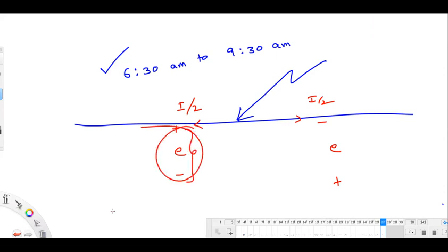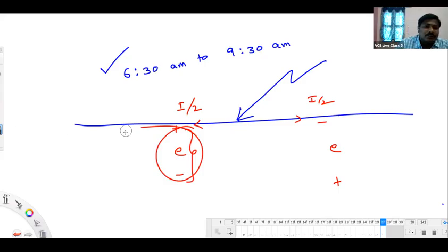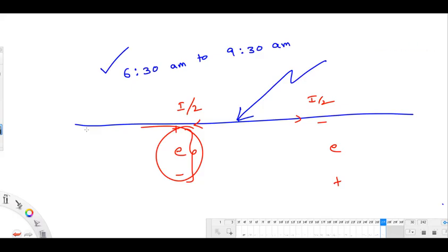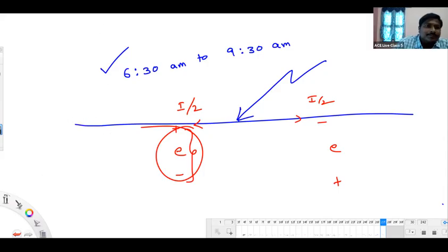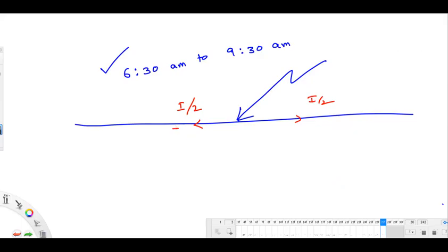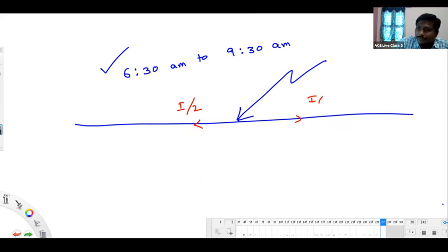I am asking in case of indirect lightning, not direct lightning. Even in indirect lightning, half of the line may experience some voltage, and the remaining half will experience a different voltage. In terms of flux, it is showing +5, that is showing -5. Very simple. Where are you connecting the insulator? Insulator with respect to ground and power conductor. That's it. So that voltage only you should think. You should not sum up this voltage, right?